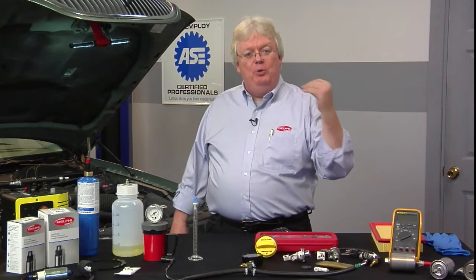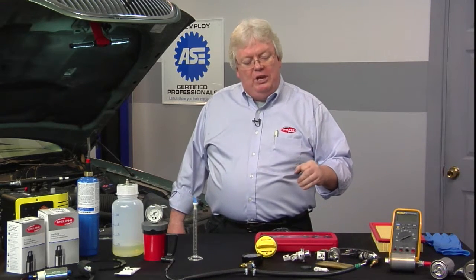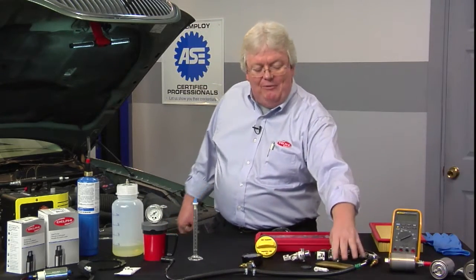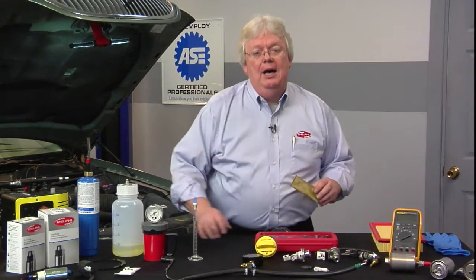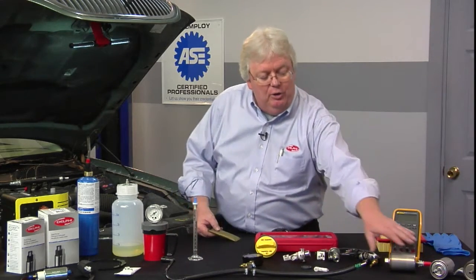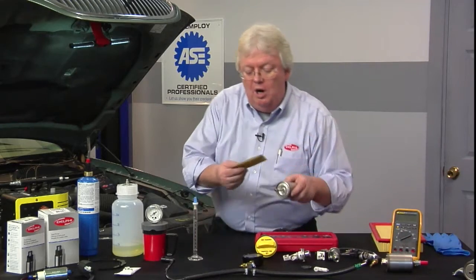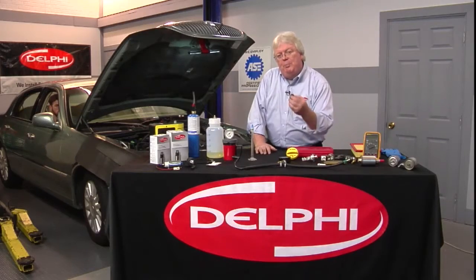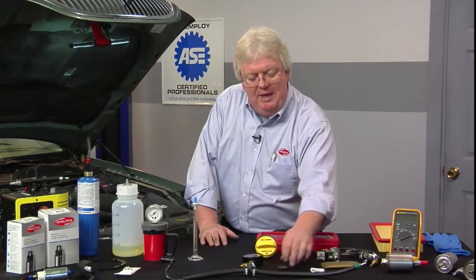We definitely would want to measure fuel pressure. Too low a fuel pressure would make it run lean and make the fuel trim numbers positive. We could also look to see if we had alcohol in the gas. It would make it lean. We could see if we have a restriction. If we have a fuel pressure number lower than specs, look at the restriction. Maybe a good old-fashioned filter, or the sock on the bottom of the pump could even be restricted. It could be a damaged pump, something wrong with the turbine or whatever, not making enough pressure.